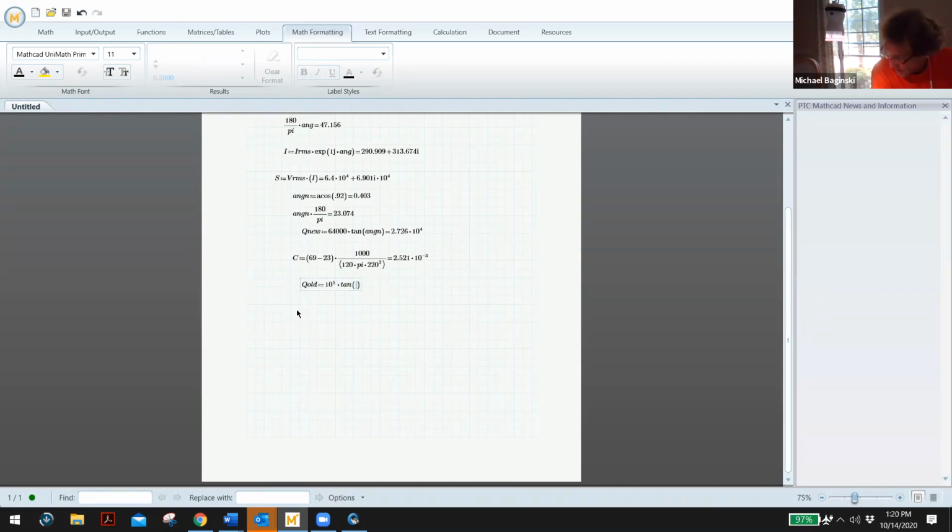That's really about pi over 4, right? 44 degrees about. So Q old, I'm getting that it's about the same. I guess if I was exact about that, I'd get a slightly different answer, but I got about 10 to the 5th for Q old. So that makes sense. It's about a 45-degree angle. So jQ old is j times 100,000 roughly, right? Yes. It's 100,000 VAR, or 100 kVAR, pardon me.